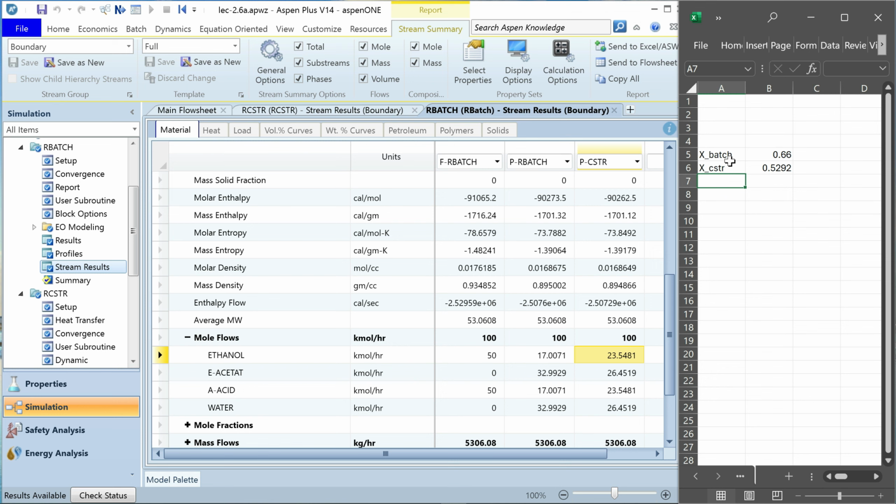And from operational parameters, I mean operating temperature, operating pressure and the residence time. So residence time in case of CSTR was 3.18 minutes. The similar time in case of batch reactor was the processing time or the reaction time that was used as a stopping criteria. This is a very classical case of conversion comparison between CSTR and the batch reactors.